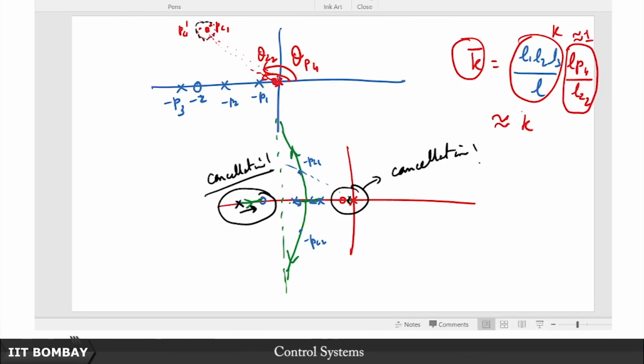So what is the way out for this? Do you keep computing like this? No. That is why we have simulation tools. And remember, this is the caveat. Anytime you're designing a controller using root locus, later on we shall see more sophisticated methods of controller design when we do state space methods. But as far as root locus is concerned, whenever you're designing compensators or controllers using the root locus method, you should always simulate. If your simulation isn't good enough, if it doesn't meet the percentage overshoot requirement or the settling time requirement, it means that the idealization you made about the second order assumption of this dominant pole pair is not valid. Maybe you need to rethink where to place this pole-zero pair.